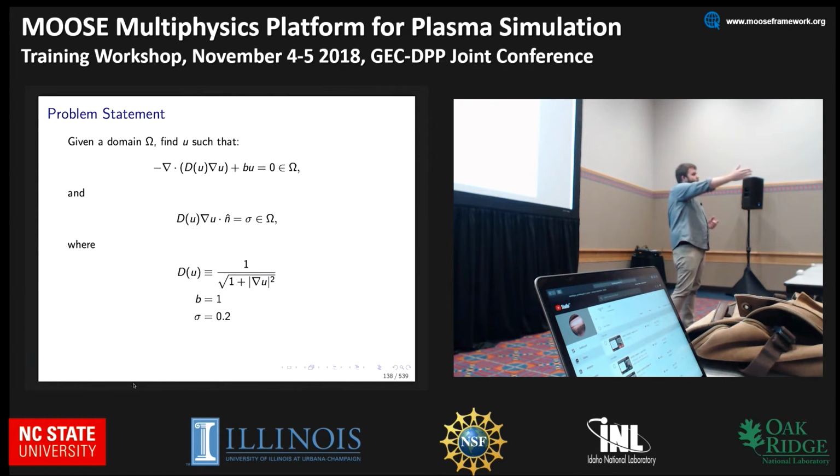So what the code example in step 2 shows you is how to create a custom kernel given a constant. You need to create a custom kernel based off of diffusion that is given your solution times a coefficient. Similarly to the diffusion kernel, you need to either create a custom kernel that has your solution times a coefficient, or in the Moose framework, there's a kernel called Reaction that does that for you, but you need to inherit from Reaction and provide a coefficient.